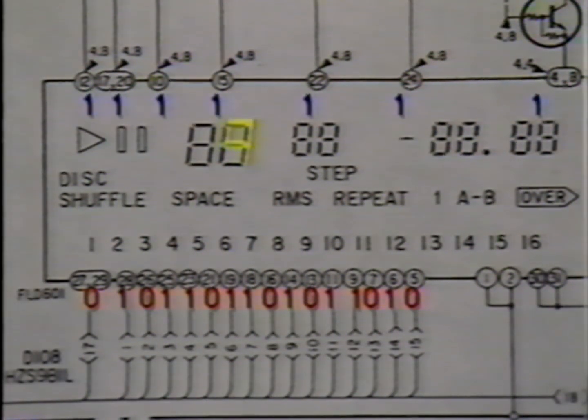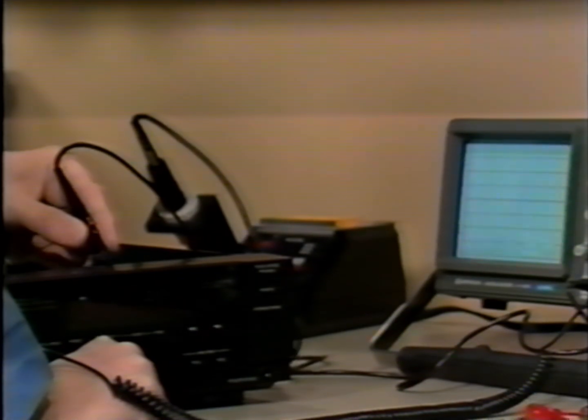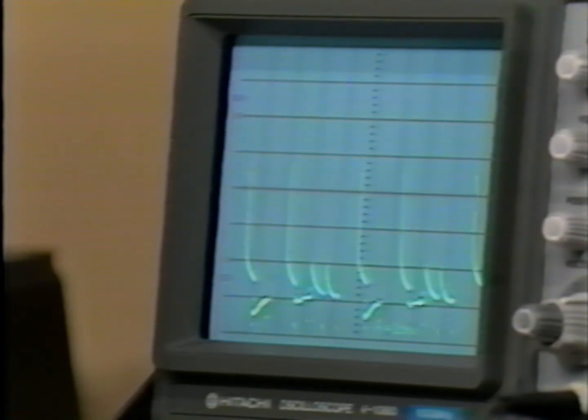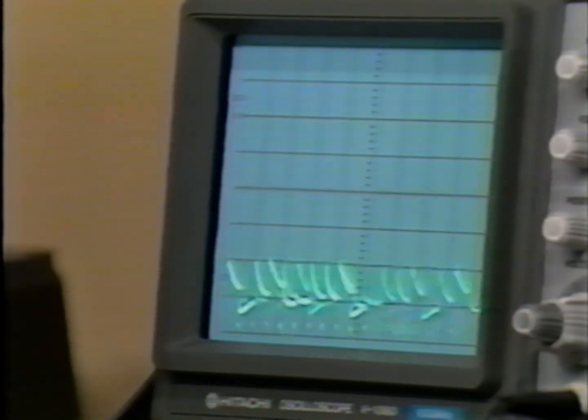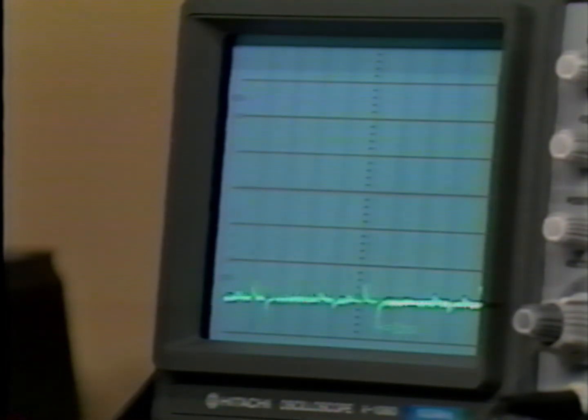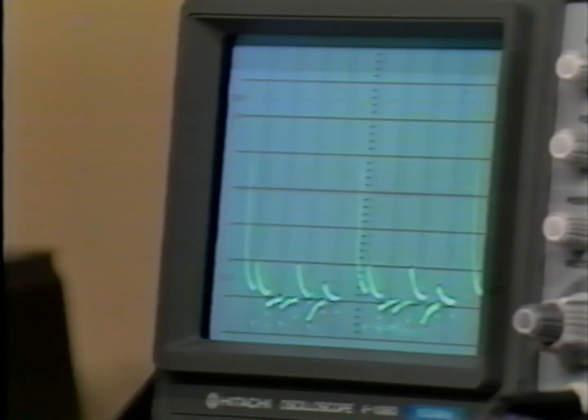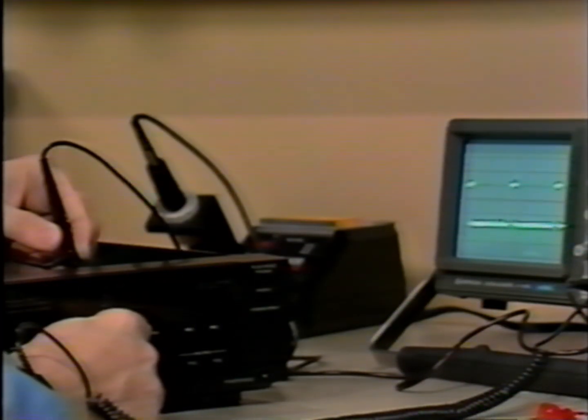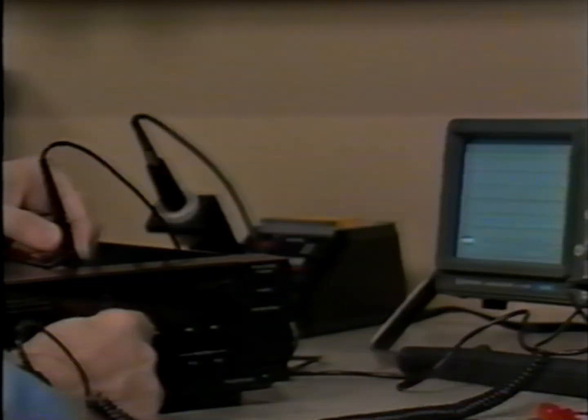A front panel display and the microprocessor's associated output lines can be easily tested using the oscilloscope. All of the segment output lines should normally be pulsing in a seemingly random pattern. The grid scan line should have the same stepped output that was observed on the front panel push-button scan lines. Display problems can originate in either the microprocessor or in the display itself.